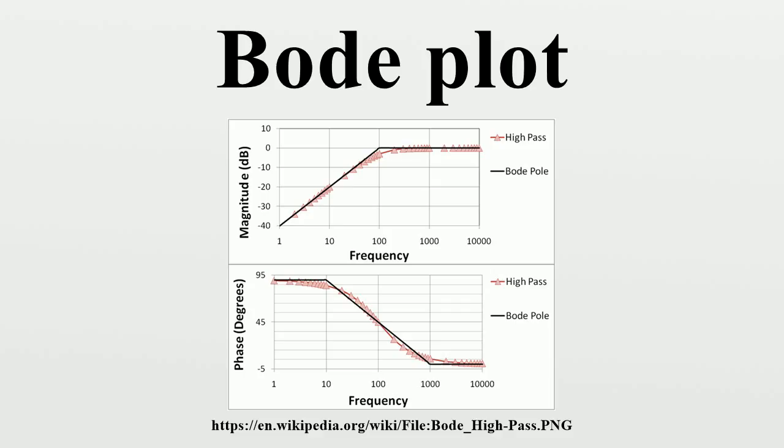In the case of an irreducible polynomial, the best way to correct the plot is to actually calculate the magnitude of the transfer function at the pole or zero corresponding to the irreducible polynomial, and put that dot over or under the line at that pole or zero.